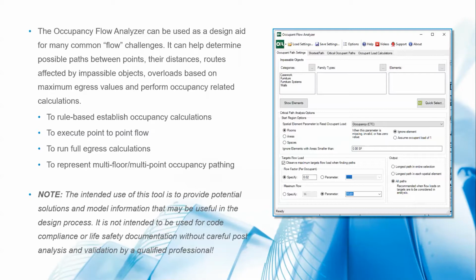You'd have to have a pen and paper, calculate your toilet count, you calculate your occupancy. There's so much stuff that as a project manager, I would have to do. I'd use Revit to create my plans, and then I'd have to create an area schedule of my rooms, and that would tell me what my areas were. And you know the drill, you have to calculate each room, calculate the occupancy based on the IBC and whatever the building type is, and then the use of the room. So it was a very long drawn out process.